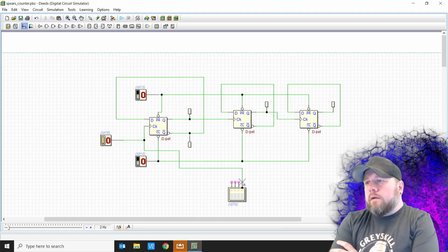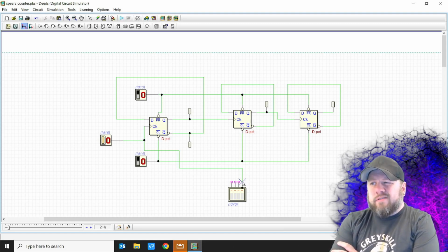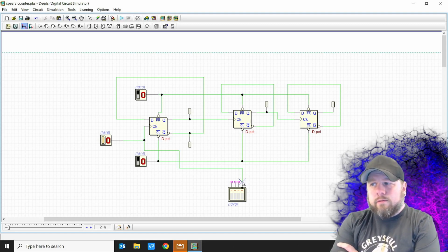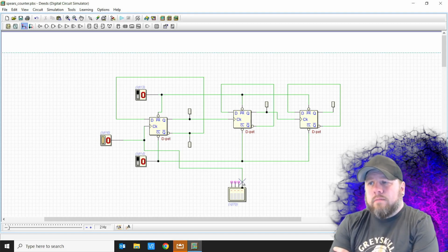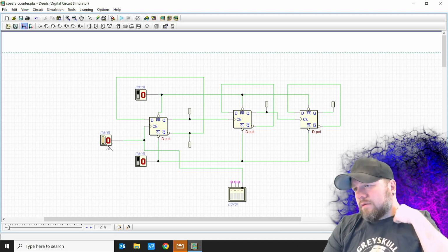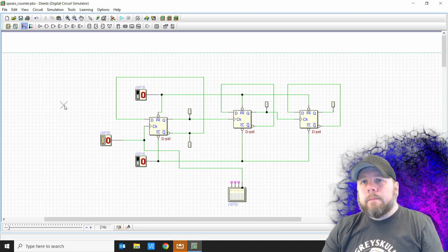Or we can take a crystal and put a voltage across it, and it's going to vibrate at a certain frequency. That's what watches use. You see quartz movement, quartz, that's a crystal, and we can get crystals that vibrate at certain frequencies, and get very new age with it. But at its heart, we take something that's going low, high, and we're dividing it down to something that's usable for our frequency, and then we're using that as a clock, okay? So right now, we're the clock. When we're pushing this button, we're driving the least significant bit, okay?